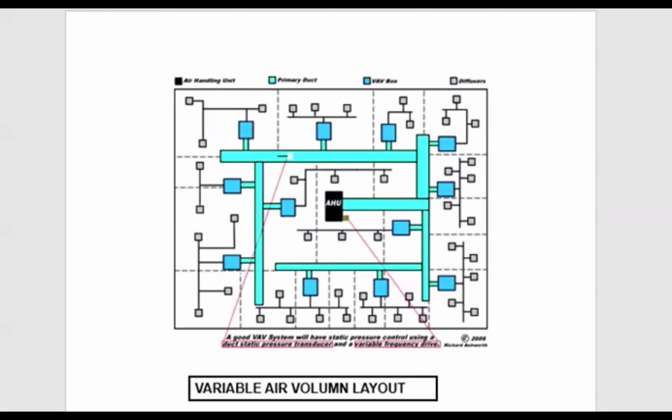All right, so say we're using 50-degree air. As the air passes through the building out to wherever that farthest duct is, it's likely that it's a little bit warmer, right? Because it's passed through warmer areas, it's passed through warm rooms, it's gone through ducts. So even if it's insulated, it's doing its job by cooling the rooms, and the air within those ducts gets a little warmer. So you would expect those openings in the control unit, those dampers, to be a little more wide open, letting more air in because it's not as cool as the air at the beginning of the run.